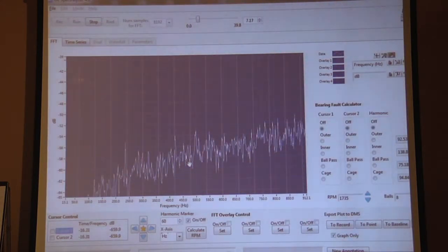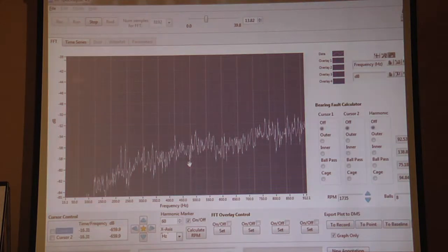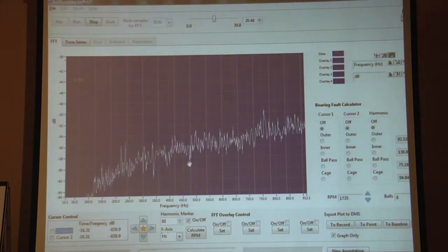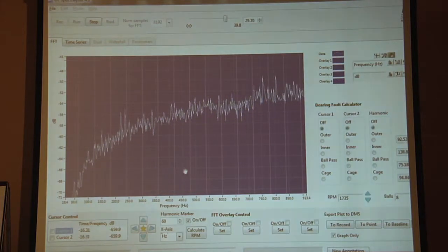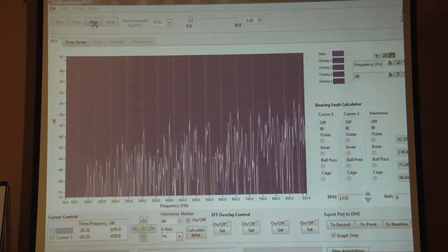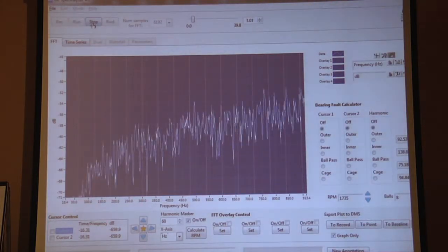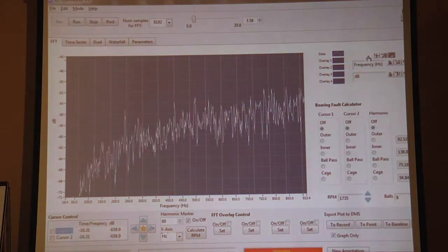You can hear the popping, right? Can you see the popping? You haven't seen it? All right, so maybe we're just not quite set up right. Audibly, there's something wrong with this 34,000 volt switch, isn't there? It should not have them pop. So when I look at the spectrums, 60 hertz here. Let me rewind this a little bit. All right, I'll stop it right there.